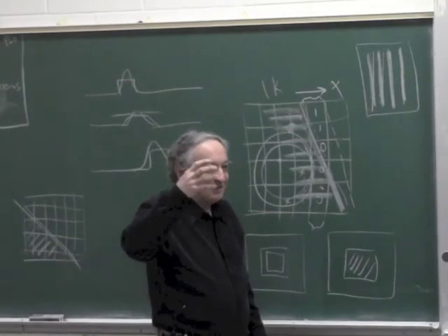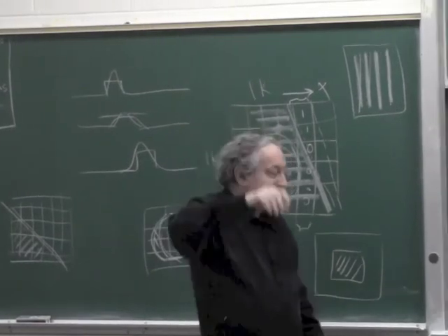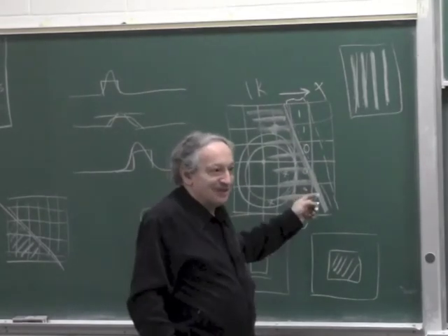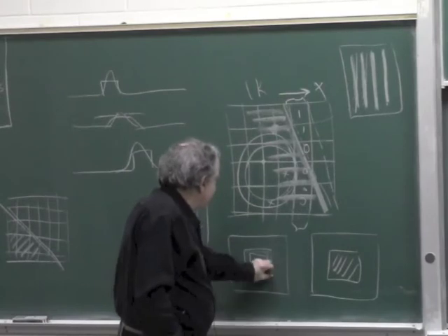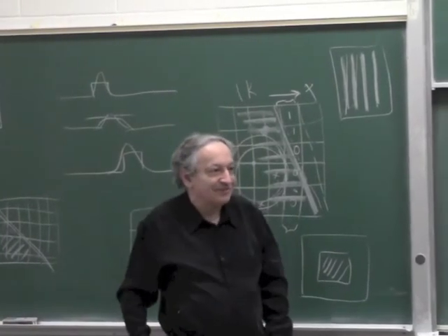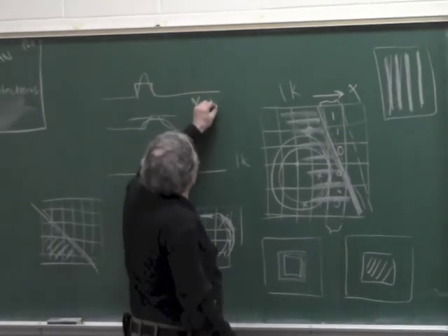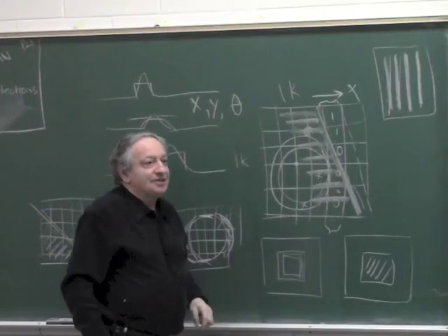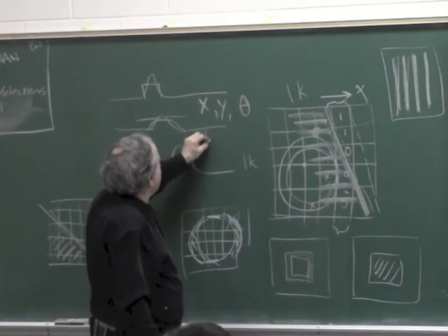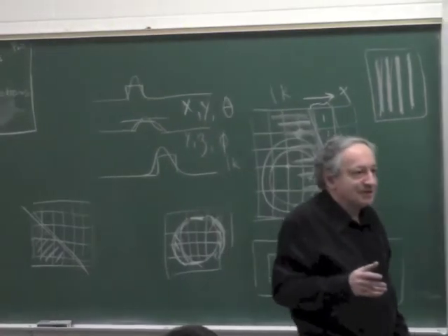with something else around. So if you look at a crane to know where the tip is, and the crane has some headlights on top, this is a bit dangerous because a camera can pick up some lamp and think it's a target. But if you use this as a target, it's hard to believe there'll be an object lit in the form of a square on the tip of a crane. So you can see that the same camera will measure x, y, theta, and all you need is a second camera from the side, and it will measure, say, y, z, and phi. So you get a 6-degree of freedom sensor with two cameras.